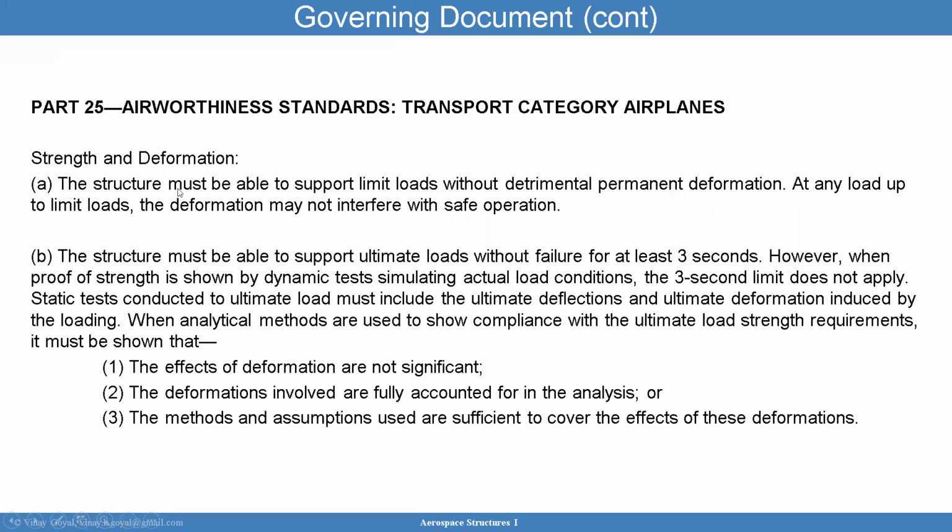Strength and deformation. The structure must be able to support limit loads without detrimental permanent deformation. I covered that in the European standard, but we're still conforming here with the FAA regulation. At any load up to limit loads, we cannot have deformations of the structure that interfere with safe operation.